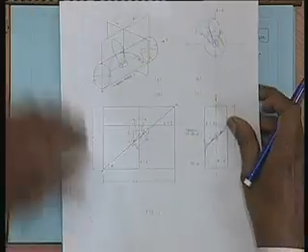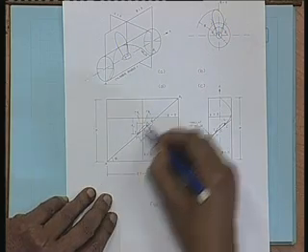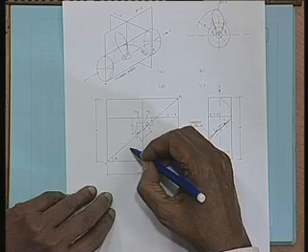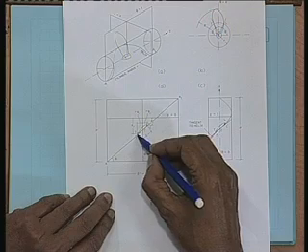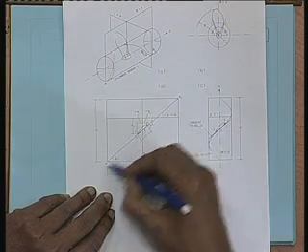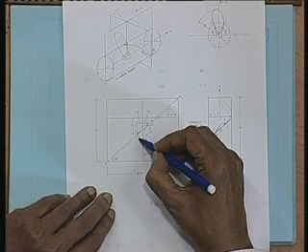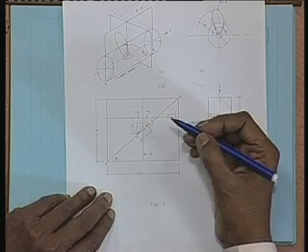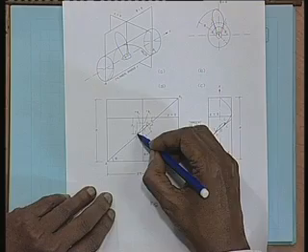So, this is what is shown here. I have just expanded this. You see here, the face is more or less falling on this helicoidal line, just slightly offset at the leading edge and the trailing edge. This is the leading edge L and this is the trailing edge T. The projections of L and T on the exact line are shown here as L dash and T dash. Okay. So, this is the actual section shape of the blade at that radius r. Am I clear? Okay.